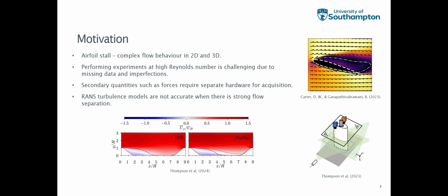And if we look at the other side, RANS turbulence models, as I mentioned, are very cheap and can be used extensively with minimal setup and expertise. But we also see that they have quite poor accuracy when it comes to some basic cases, which most of you have spoken about today, like the periodic hill, for example.